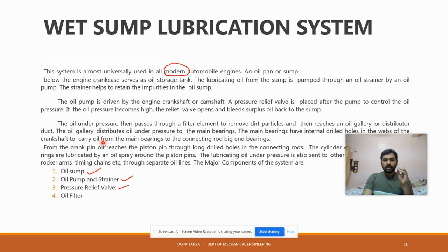Here the working is the same, but you can see the design changes mainly in wet sump lubrication. See the piston connecting itself: the piston has a gudgeon pin and piston rings, and you have camshafts for the inlet and exhaust valves. There is a need for lubrication inside the internal combustion engine as well as outside, for a chain, for a toothed gear or a pinion attached at the other end of the crankshaft, where it distributes the torque. That is called brake power, as you all know.